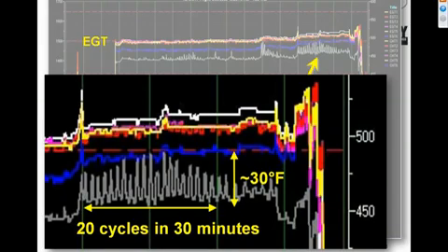And in fact, this 210 valve is the one that we saw earlier where we had 3 views of it. Now, the reason that a failing exhaust valve, an exhaust valve with a hot spot where some portion of the valve is not making good contact with the seat, the reason the EGT oscillates like this, is because